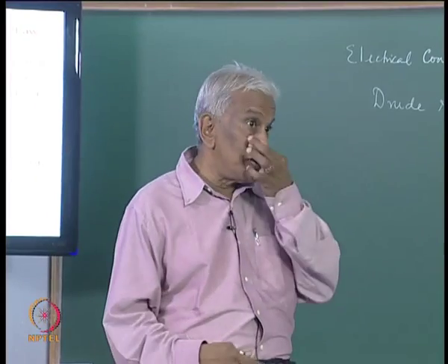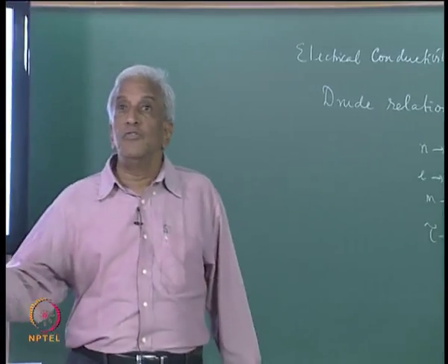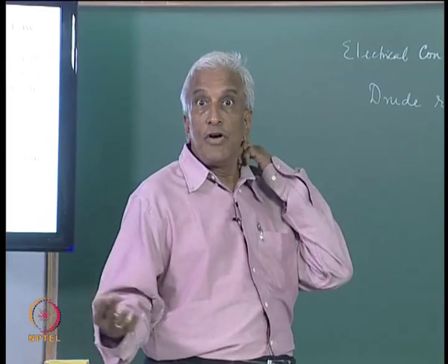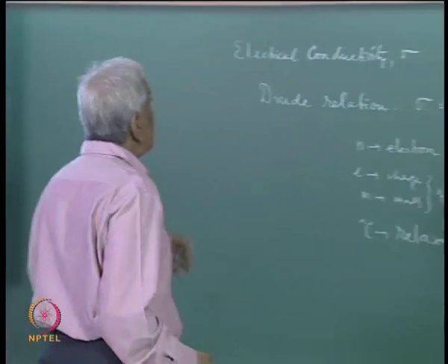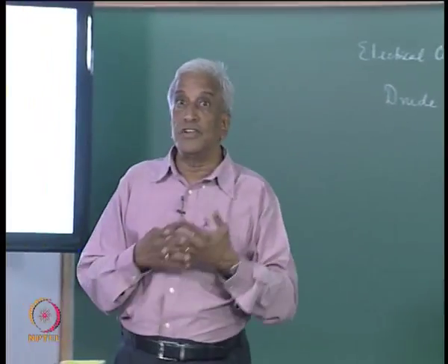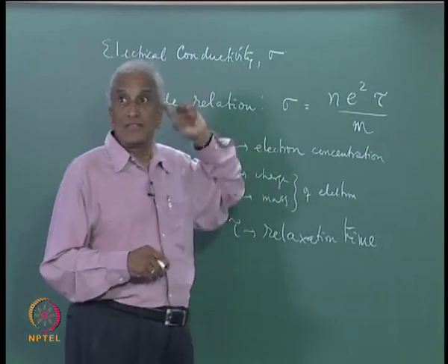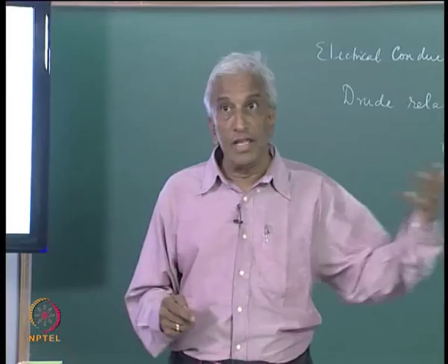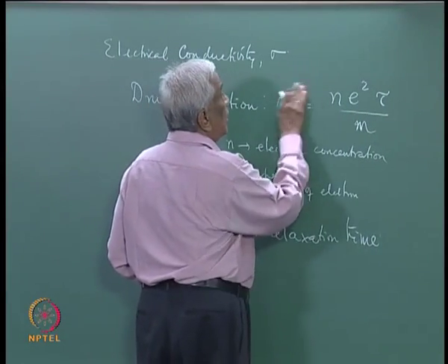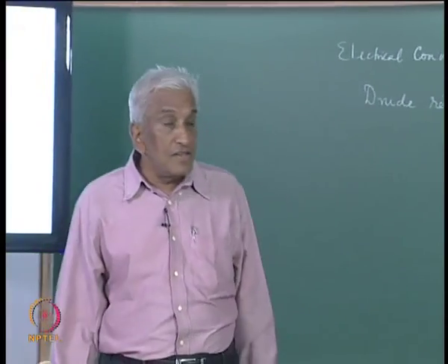So, its calibration, conversion of the resistance to a temperature, is fairly straightforward and universal, and this is the reason why the platinum thermometer is preferred all over the world as a resistance thermometer. Now, this characteristic linear temperature dependence of the electrical resistance is got by the temperature dependence of sigma, which is entirely determined by the temperature dependence of the relaxation time.